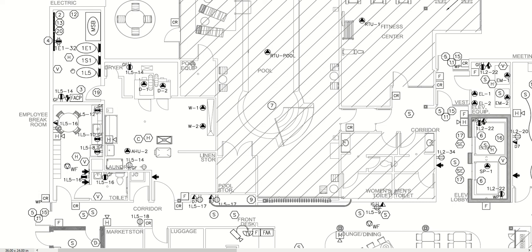And you'll notice that we do have a naming convention on this set of drawings, and so the E indicates emergency, so it is connected to the generator. So if you lose main power, this outlet would still have power once the transfer switch switches over and the generator starts. Whereas this outlet here, the 1L5, that would not.